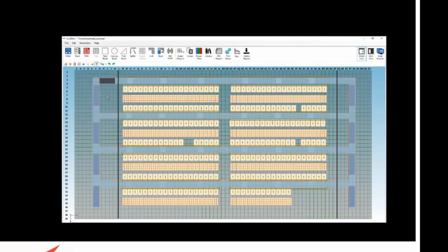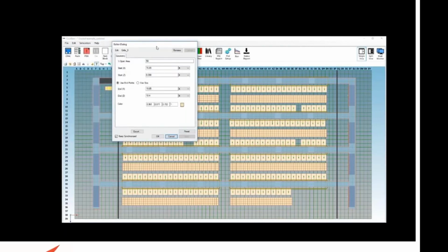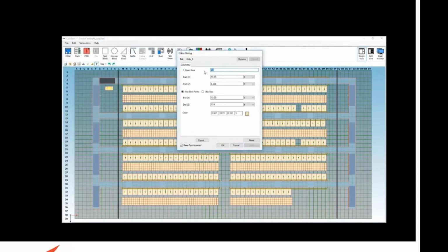So now I have to put a grill in because I have to let the hot air down into those intakes. Here I set it up. I want it to be a pretty high percent area open. You could cut a hole without any grill at all, which would be best, but we'll set it at 80. I'm going to use size and make this return probably 4, maybe 6 feet wide. But I need the length to be long enough to go all the way down the whole length of the room.